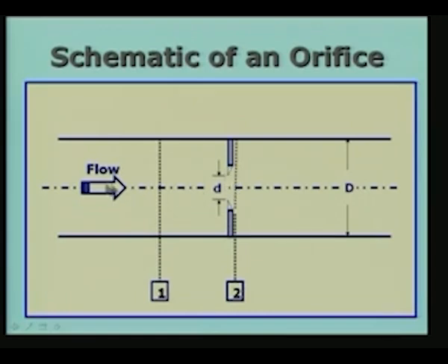Okay. So, the flow which is coming here, because it has to pass through the small hole, is going to accelerate when it comes towards the hole, and therefore, how does it accelerate? The pressure energy is converted to kinetic energy, because kinetic energy is increasing, and it comes from the pressure. The potential energy is converted to kinetic energy, therefore, the velocity is larger here as compared to here, and that is what happens.